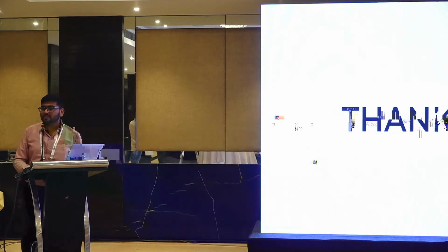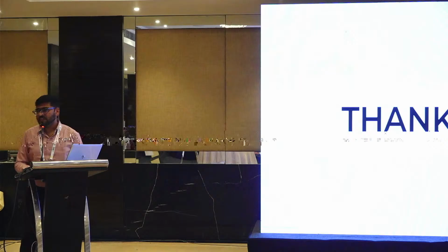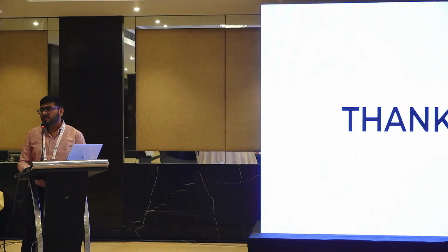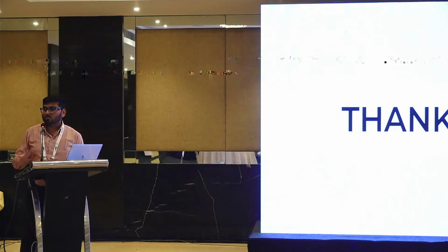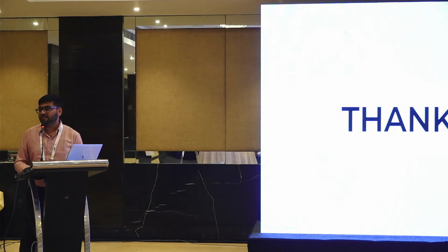I can get your question. The compressive strength, there is not much increase. There is a slight decrease in modulus of elasticity. This type is more suitable where the impact load is predominant. It will not be applicable for the entire concrete media.